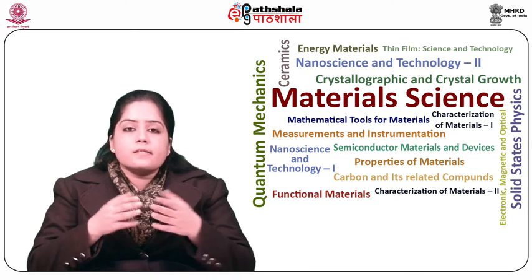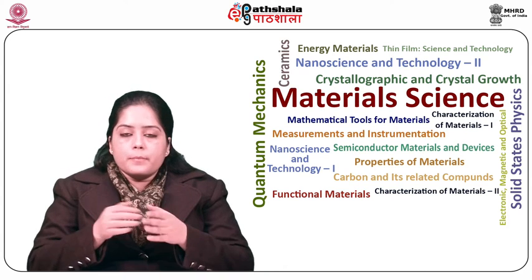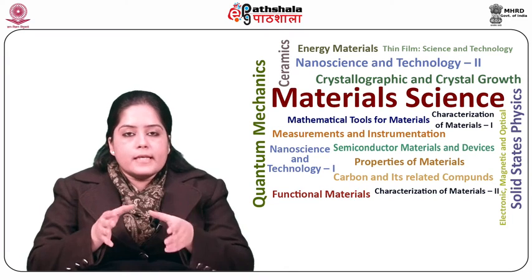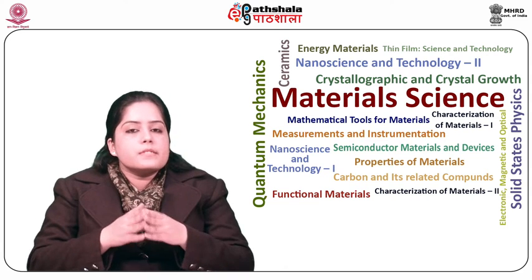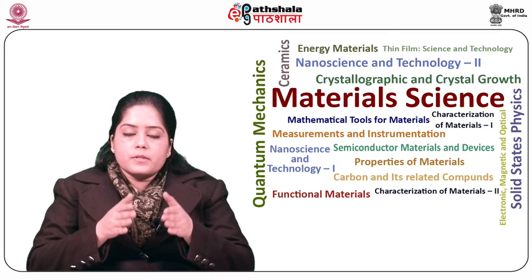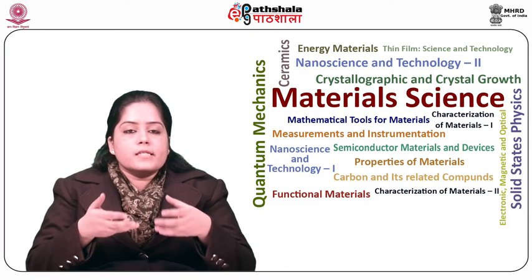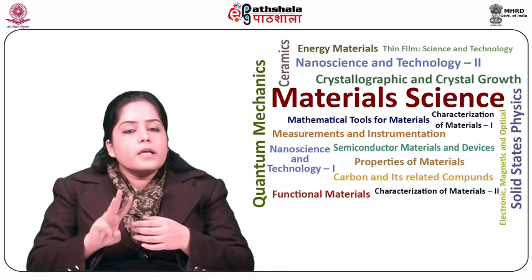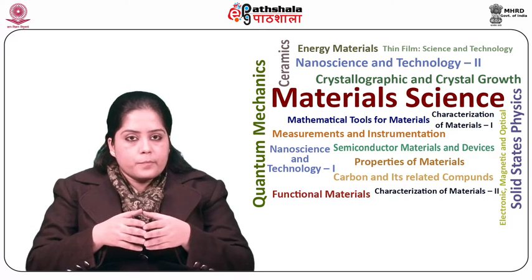Next is SRAM, static random access memory, which can retain the stored data indefinitely. SRAM cells use a simple bistable circuit or flip-flop to hold a data bit. Generally, there are three operational modes of the memory devices.